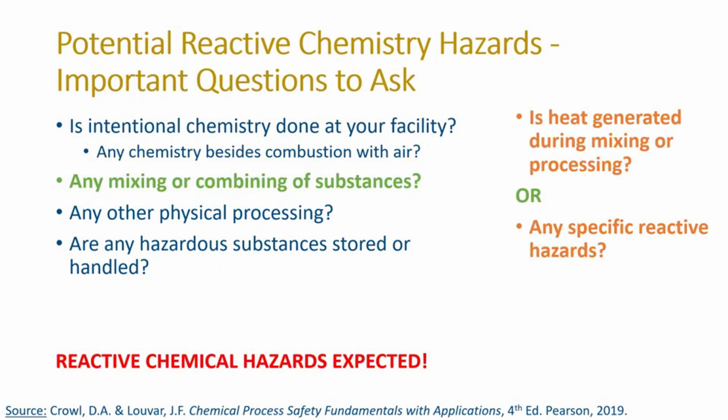A second situation where we could expect reactive chemical hazards at our facility is if we could answer yes to the question of any mixing or combining of substances at the facility, and yes to either heat being generated during mixing or processing, or yes to there being any specific reactive hazards associated with the substances that we are mixing or combining.